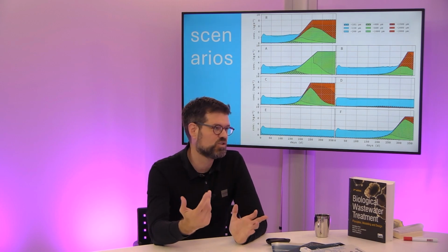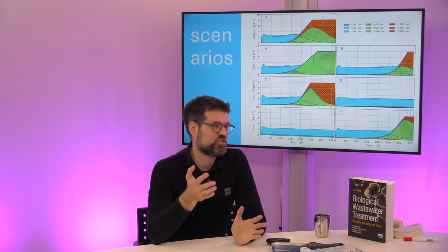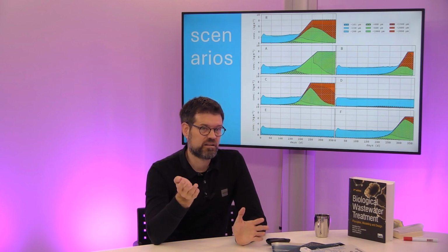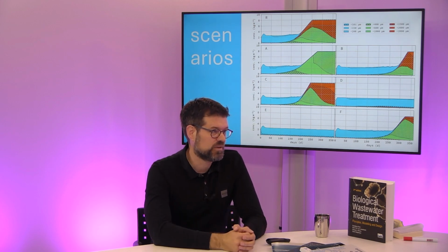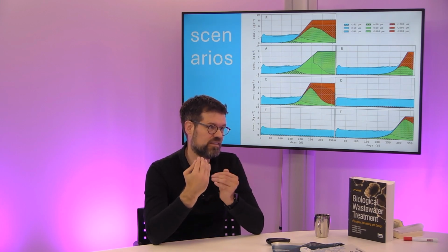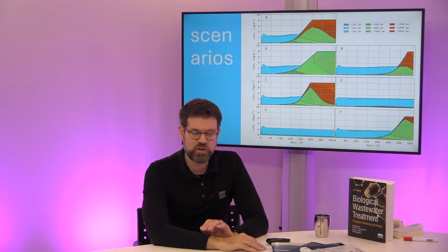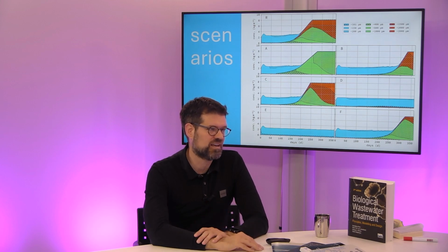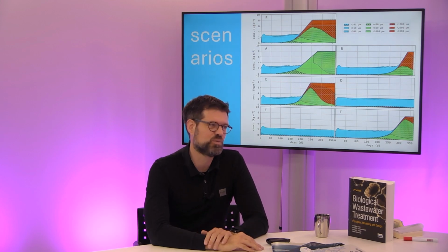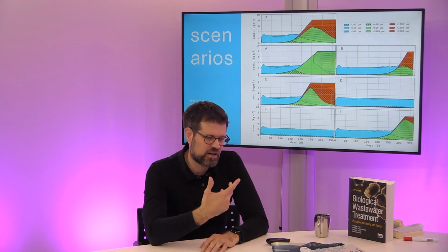In practice, you cannot say that large granules settle at the same speed as small granules, but in a model you can do that. So you can see what the effect of that differential settling velocity is, and that really gives you insights into what is happening in that reactor. So we ran a ton of scenarios. These are the important ones I'm showing here in the slides, and that really accelerated our insight into the granulation process.